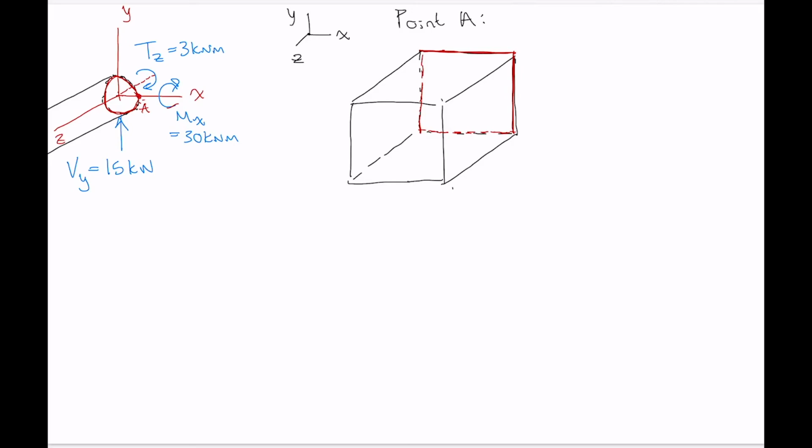Okay, so let's go through our internal forces one by one. Let's start with our shear force Vy. When you're thinking about each of these internal forces in turn, I think it's helpful to just draw a two-dimensional sketch looking at how the internal force is related to point A and the stress distribution that's caused by that internal force.